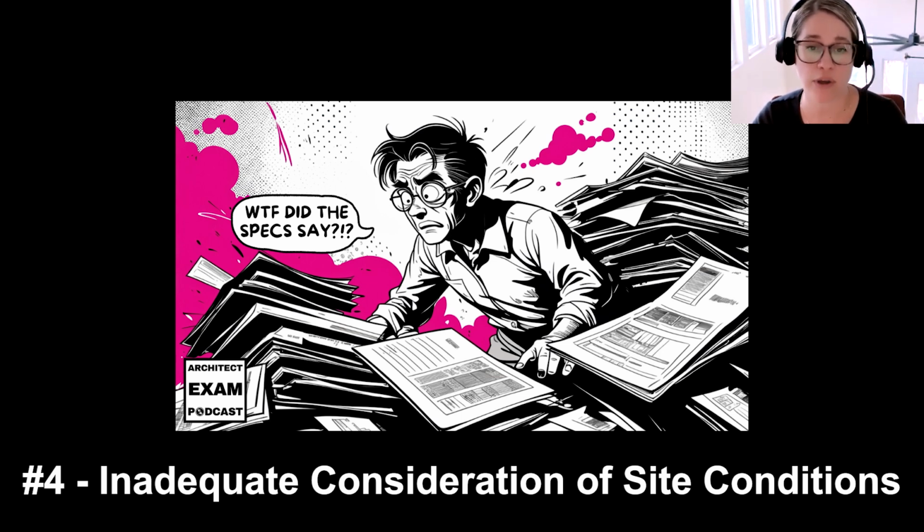If the firm you work with works across different climates, consider creating regional supplements to your master specifications. For example, have a coastal supplement that automatically will update your specifications to something that's appropriate in a coastal zone, right? For example, metal components. So remember that materials don't work well just anywhere. They are really fine-tuned to your climate, your region, and how they interact with their environment. So your specifications need to account for that.